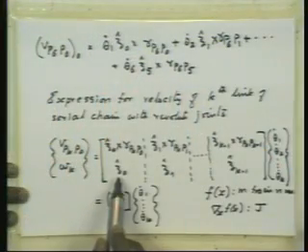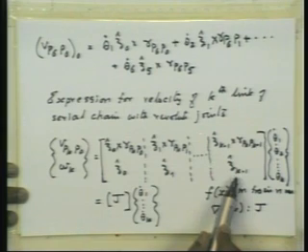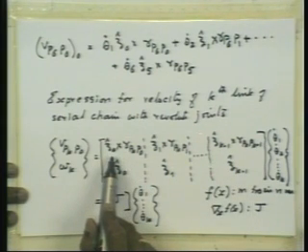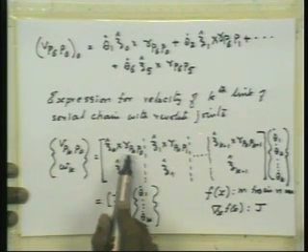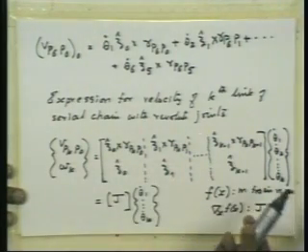Now this is for a serial chain with revolute pairs. There are some very important conclusions that can be made from this. Remember, the columns of the Jacobian are these 6 element columns, very simple to obtain. They are nothing but these unit vectors along the separate axes, and the cross product of the unit vector along those axes with some particular vectors.